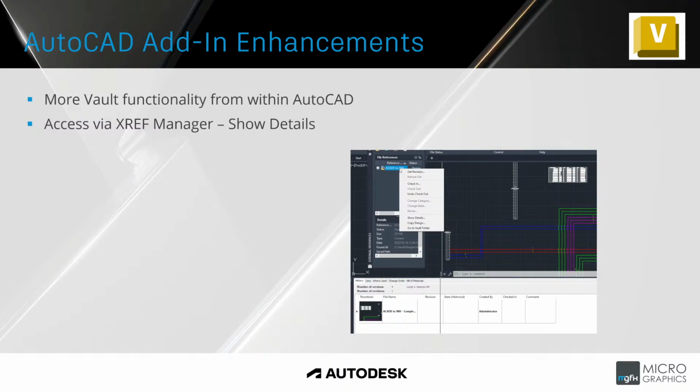Okay, so the first thing we're going to take a look at is the AutoCAD add-in enhancements. Once again, it's more Vault functionality from within AutoCAD. Great stuff. As I said, we don't want to jump from program to program. If you can get everything from within the one program you're working with, good for us. To access the additional functionality, we go to Show Details. And the one thing you need to know is that once you've checked out or opened the file from the Vault, you need to make sure that you've got your XREF manager open. That's clue number 1 to get this up and running.